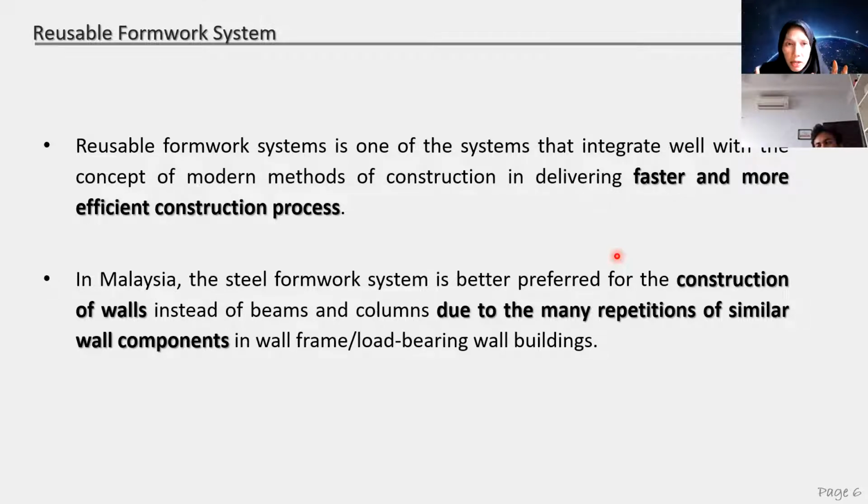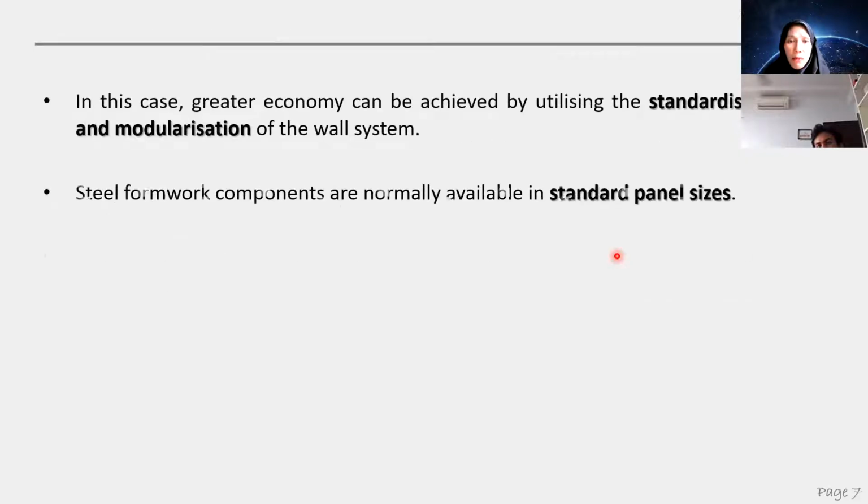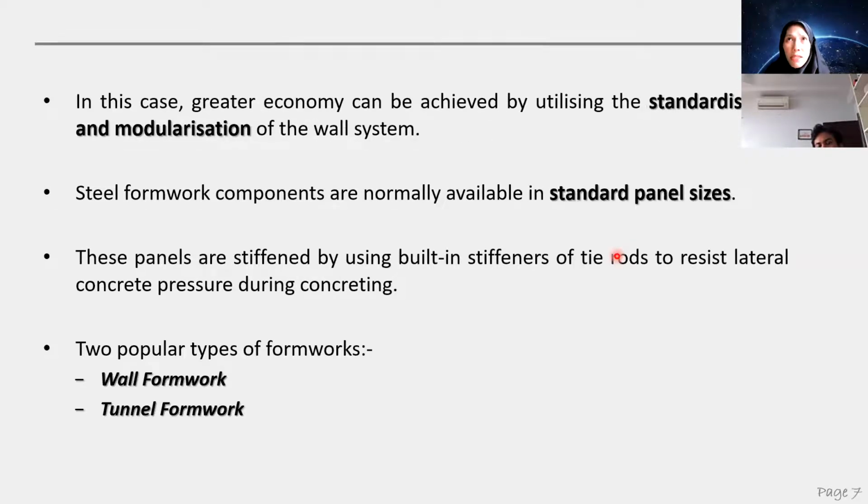Basically, the formwork system in this case uses steel, plastic, and very heavy duty materials. Compared to the traditional plywood or timber one, it is very, very costly. So you have to make a decision in terms of what kind of building it is economic to use the formwork system for. But most high-rise buildings nowadays are using the formwork system, because it can reduce much on the costing.